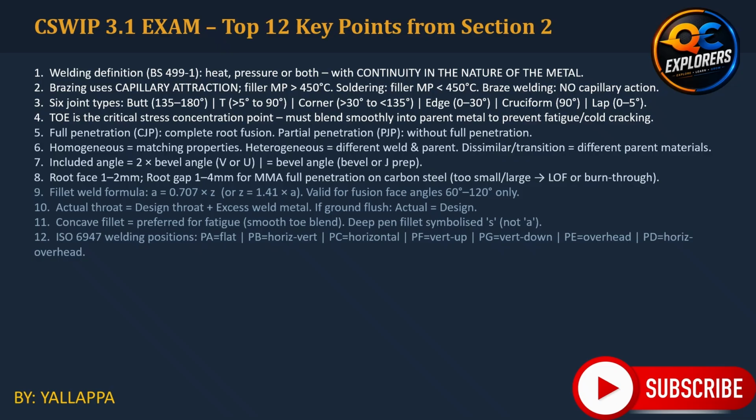Tenth, understand the difference between design throat, actual throat and excess weld metal. Eleventh, recognize the significance of fillet weld profile, including concave and deep penetration configurations. And finally, know all 7 ISO 6947 position codes.